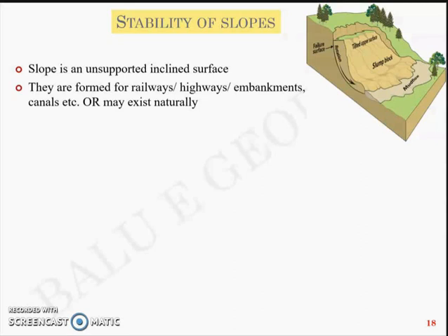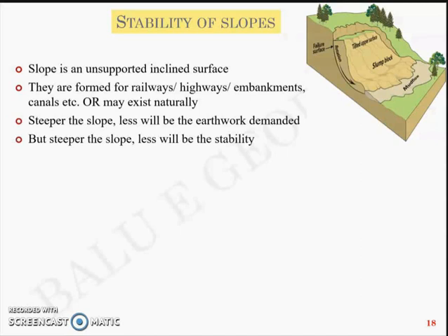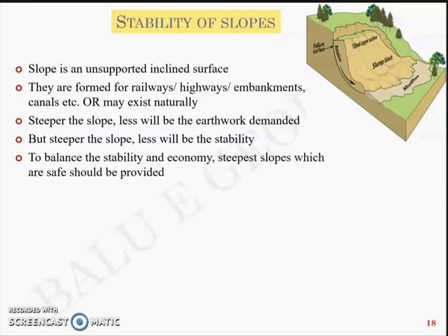Now the steeper the slope, the less will be the earthwork demanded. If you're able to cut a very vertical cut, the earthwork involved, the mass of the soil that you take out, will be very less, right? So the steeper the slope, less will be the earthwork. But once you go steeper, there will be a higher chance for it to be unstable, right? So less will be the stability. Now to balance this concept, to balance the stability and economy, we as civil engineers are interested in the steepest slope which is safe and economical.